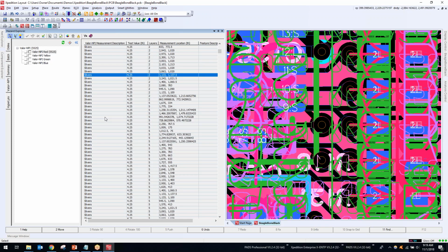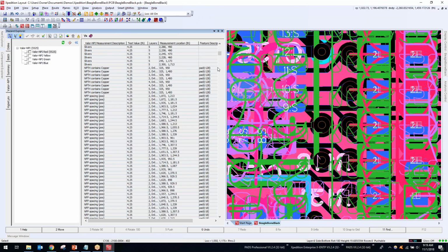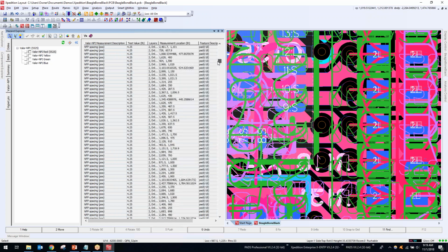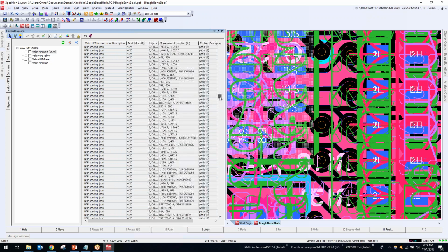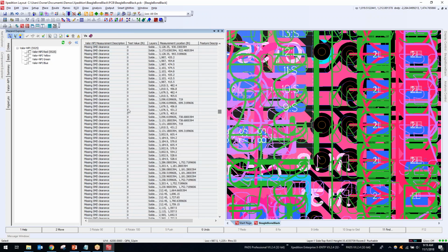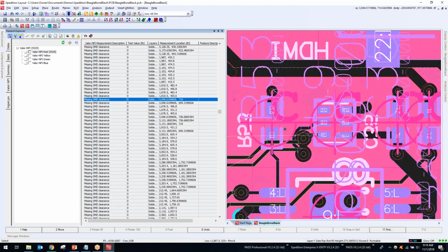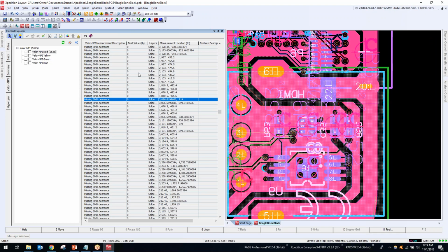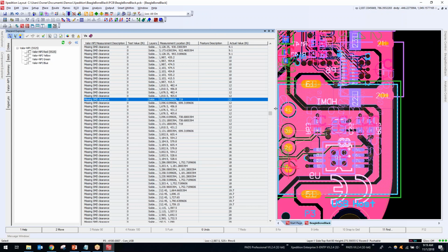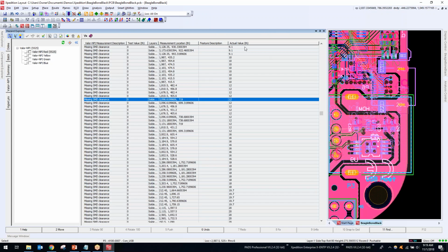Okay, slivers, we can check on those, and it'll, again, cross-probe directly into the layout tool. All right, so just like with all other Hazard Explorer results that we've looked at so far, missing SMD clearance on this pin, I can actually accept or reject and add comments.